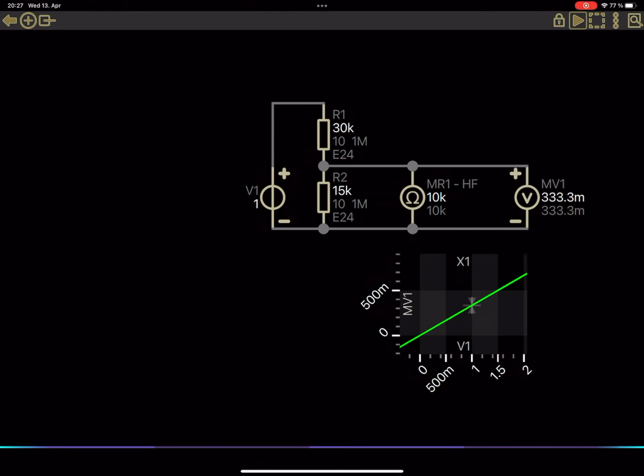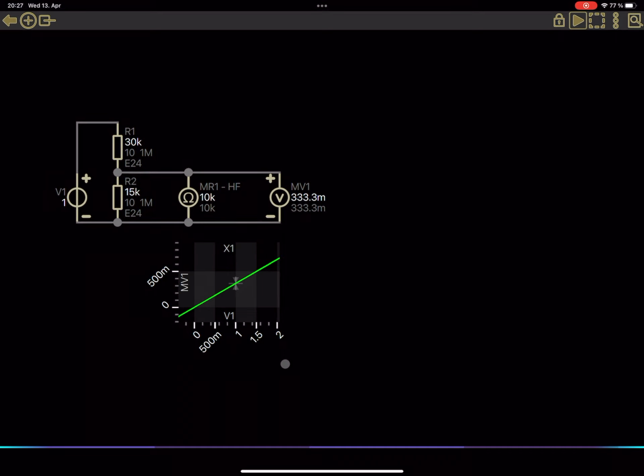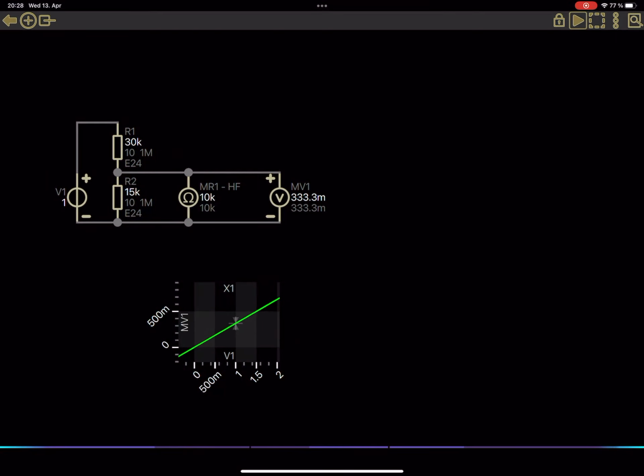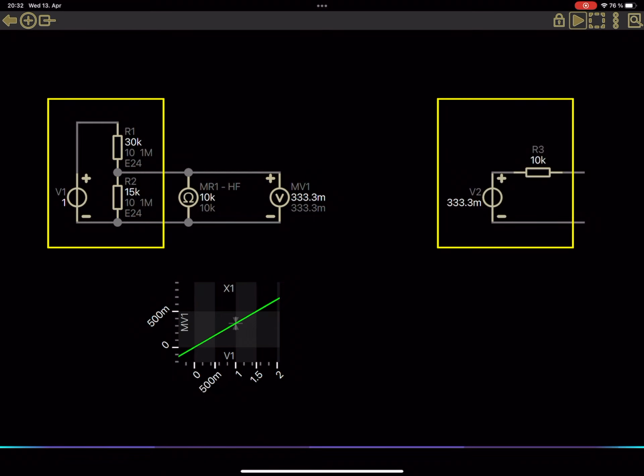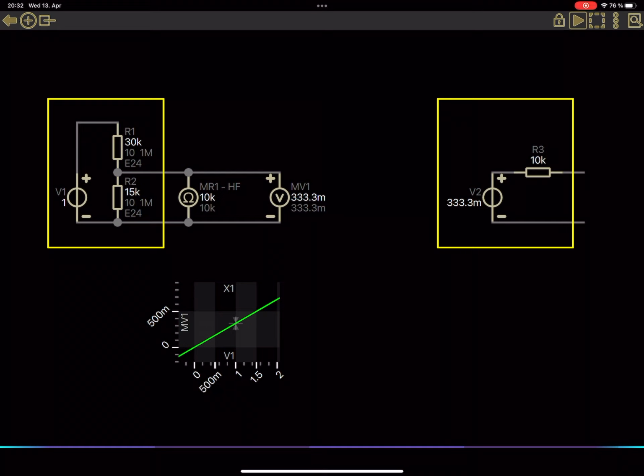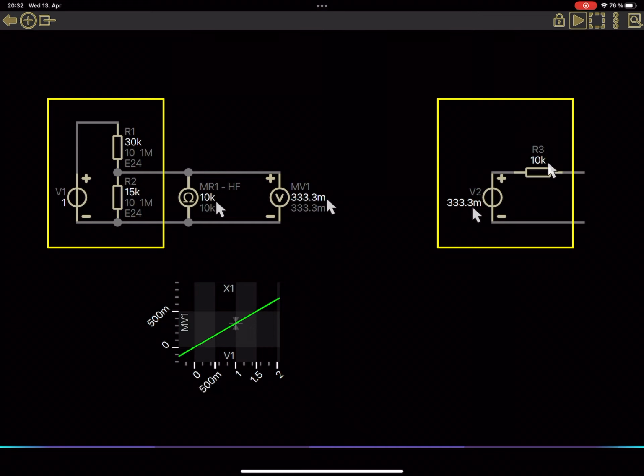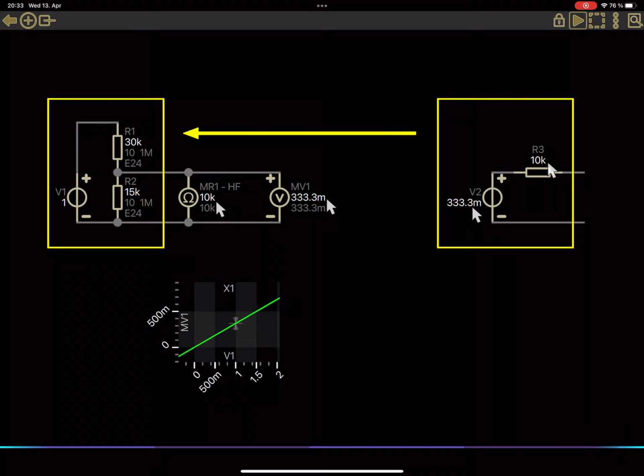So now, let's investigate the all-important Thevenin's theorem and how to determine and synthesize Thevenin equivalent circuits. Well, the good news is that we are already done. Thevenin's theorem says that, from the perspective of a single output, any linear circuit can be replaced by an equivalent voltage source with inner resistance. The corresponding values of the so-called Thevenin equivalent of our voltage divider are already given by the meters. However, the important point is, roughly speaking, that we can now easily synthesize any voltage source with inner resistance by designing a voltage divider, just by changing the target values of the meters.